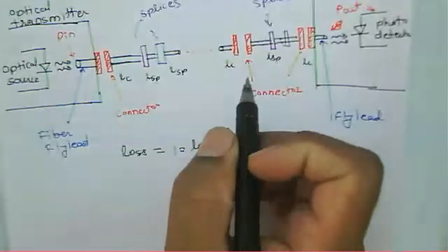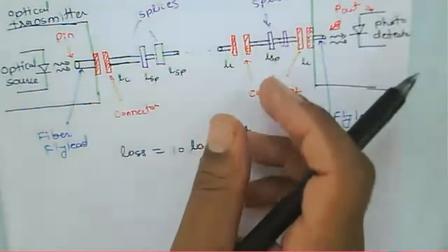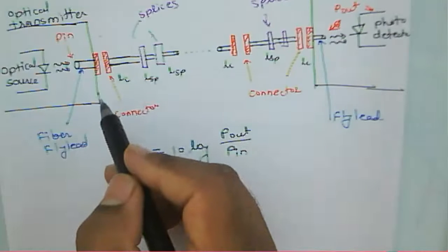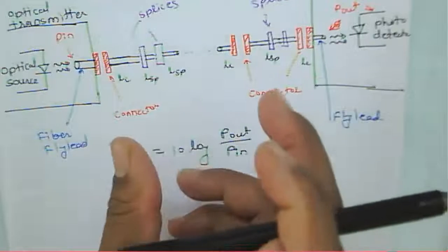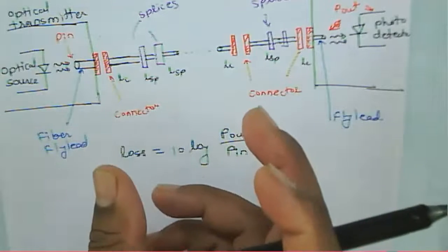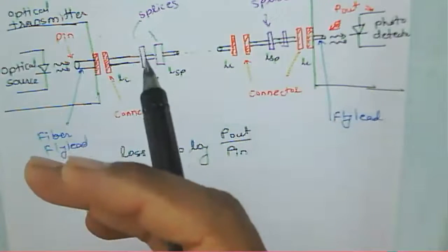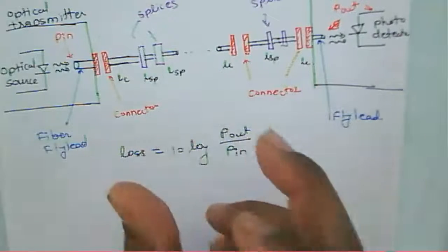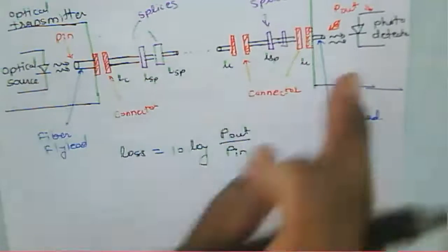That link power margin is provided because we have a few components, that is connectors, splices, or whichever components we are connecting here, and those components are degraded because of aging, temperature fluctuations, and any other problem that occurs on those particular components. Because of that there may be losses, and that loss is nothing but the marginal loss or system margin loss for a given system.